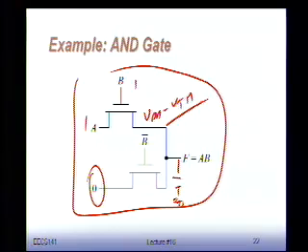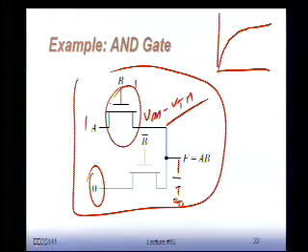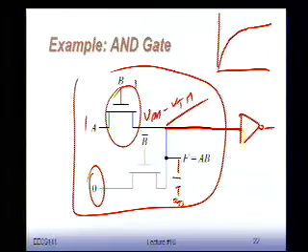Well, yes and no. It has some challenges. Number one, if you look at pulling up a node all the way to VDD minus VTH, you see this NMOS device really towards the end, when it gets close to VTH, gets very little current. It's extremely soft, so getting up higher is really going to take forever. The second thing is that you have to be aware that I'm going to put this in an inverter to create regeneration.